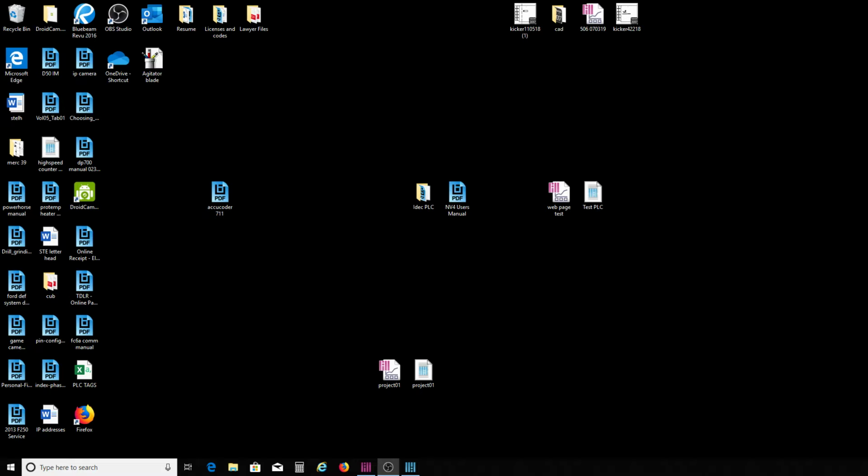First, we're going to start off just getting you on the actual intranet inside of your own home or office or whatever. And we'll show you how to find out what your IP addresses are, what they mean, how to set them on your PLC, things like that, where everything's talking together. I'll kind of give you a rundown of my setup.